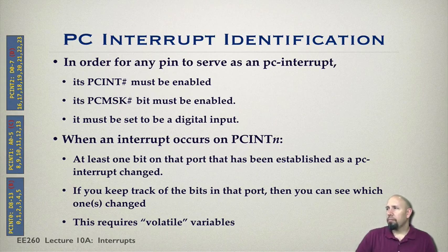Okay, so now let's suppose we have in PCInt1, let's say, 2 or 3 of those pins. So let's suppose we have this whole port enabled. So notice that's port C. These are all the things in port D, and these are all in port B. Okay, so that's why the 0, the 1, and the 2. It seemed kind of out of order the other way. In other words, these digital ones are not in order with these guys. Okay, but that's because B is considered PCInt0, C is PCInt1, and D is PCInt2.